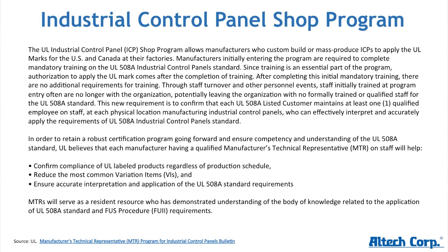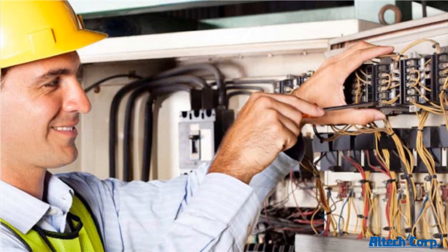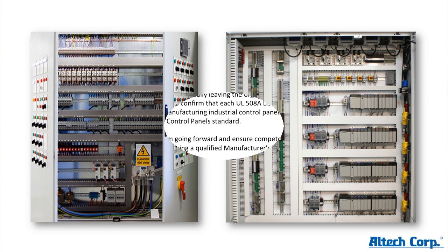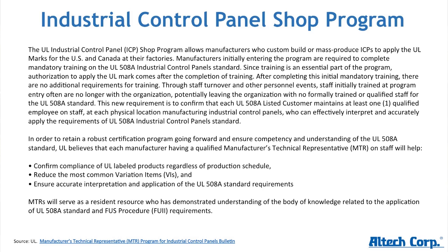Again, you need to document everything, but then you will have essentially only 4 unannounced visits of the UL inspector to your facility per year, and he makes sure that you have all the documentation for your panels, that you're applying the right label to it, the right UL sticker, which, by the way, you can purchase from UL, and that your MTR, the manufacturer's technical representative, is still there, his training is current, etc. So it's a big process, but if you buy a UL 508A approved panel from a UL approved panel shop, you can be assured that you have a safe and UL conform panel.